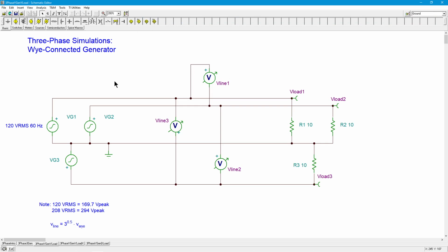So I did say that if you messed up one of these phases, you're going to get some weird stuff. All right, so let's look at one that's bad. Okay, so it's the same circuit, except I inadvertently put this thing in backwards. Well, I purposely put it in backwards, but I'm just saying, if you had just taken the 3 of them, like I said initially, and you just threw it down here and wired it up, this thing is actually 180 degrees out of phase of what it should be. It should be 240, but it's actually 60. You could either think of it as plus 180 or minus 180. It won't make any difference. But this thing is actually sitting at an angle of like 60 degrees, okay?